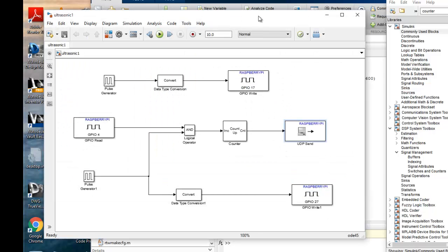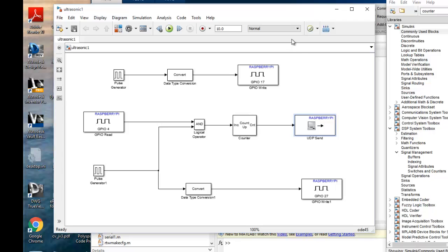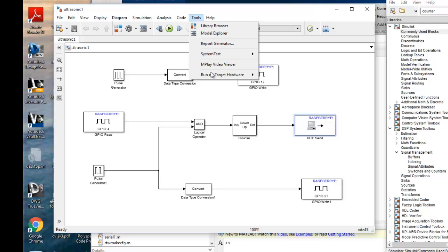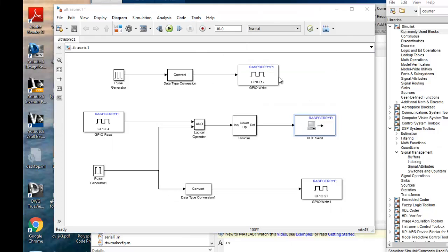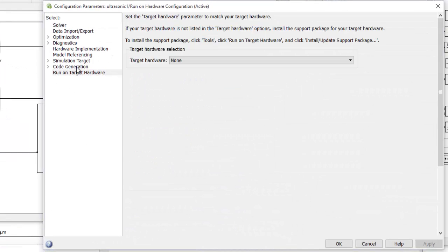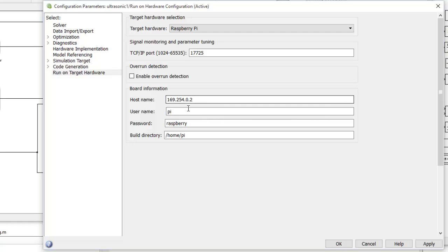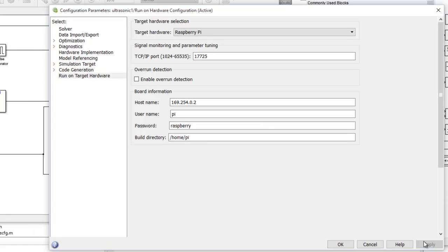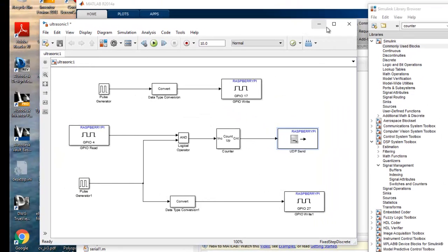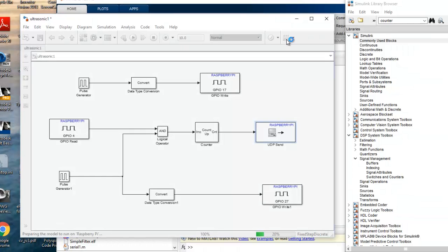And now everything is ready to run, but remember, I didn't define the hardware yet. So we go to Tools and Prepare to Run. Now the target hardware, we pick the Raspberry Pi. We can see the IP address, home folder, and TCP/IP port for communication with Matlab. By clicking on this icon, Deploy to Hardware, Matlab is now sending all the source files to the Raspberry Pi home directory and starts the building to then continue with the execution on the target.